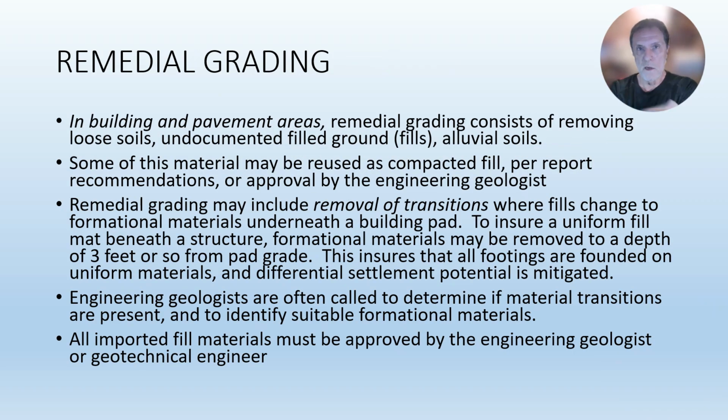Remedial grading, this goes into more detail on mitigating conditions of soil and rock which are unsuitable and bad for your project. So you can remove loose soils. Undocumented means old filled ground that hasn't been tested, that may not have met maximum density or optimum moisture conditions. Alluvial or water-laid soils. As I said, some material may be reused.